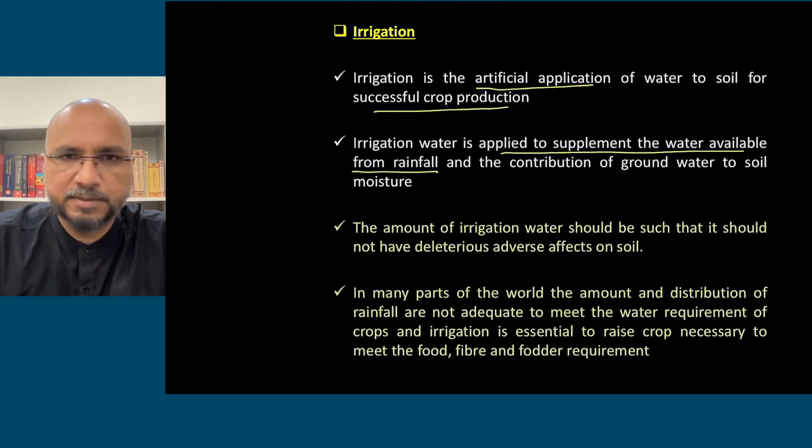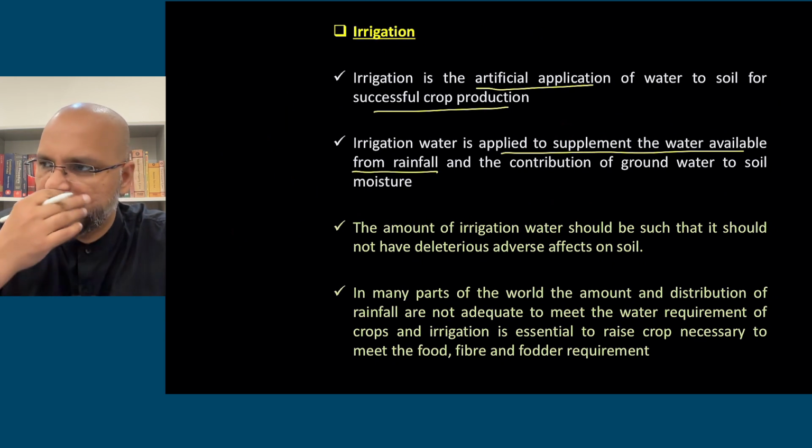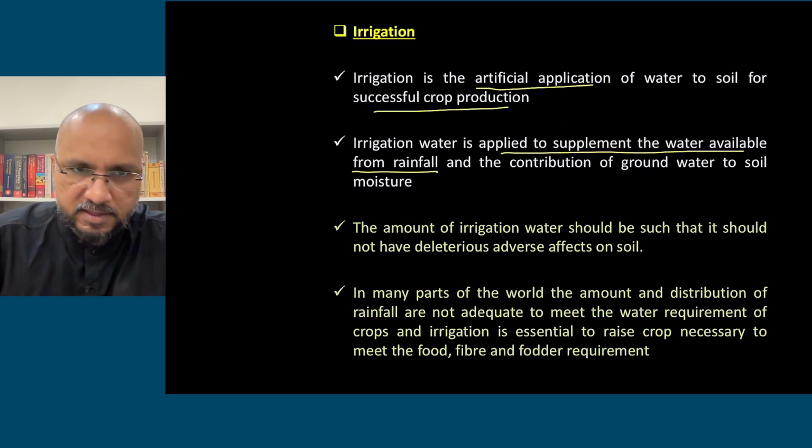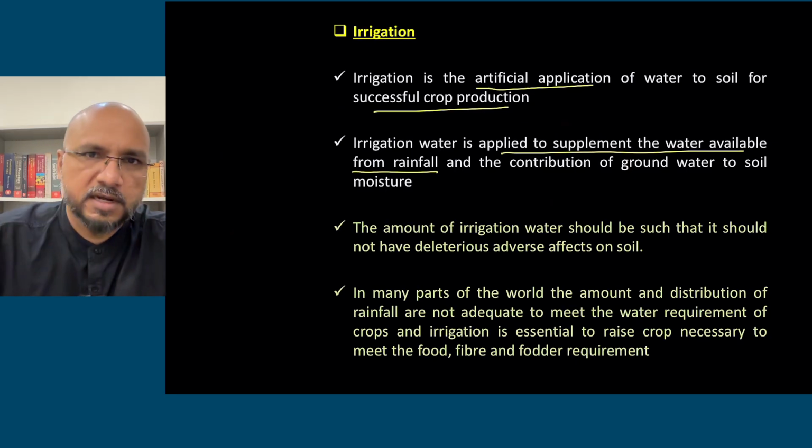Rainfall is the main source of soil water. Then where the field is near a canal or river, there is also additional contribution, or where the groundwater table is very high, water may rise through capillary action to the upper levels of the soil.